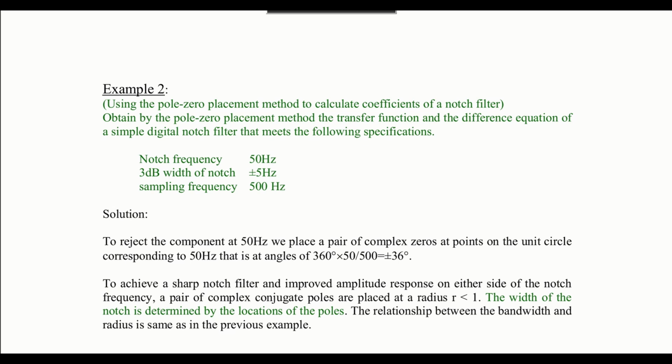So in our last example, we solved for a passband filter design using the pole zero method, and we realized two things. When we are designing a filter in the real world, we want something to work with in the real domain, and secondly, we usually want our zeros to stay on the unit circle and our poles to stay inside the unit circle. That's the whole setup for the design, so that our design will follow some convention.